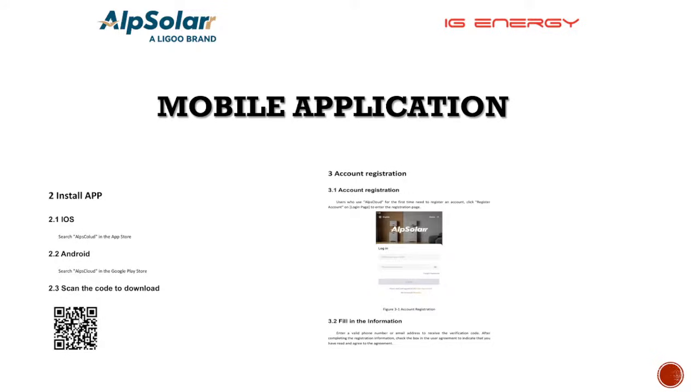But can I ask a question? Yes. What's the disadvantage of it? The disadvantage is that when there is an issue or something, the client will start calling you as an installer, because once the client sees a small minor thing, they start calling, asking what's going on, why is this showing this? So now it's not left to you as an installer, from the comfort of your home, to go to the app and do a little bit of settings. Set the SOC, set the cutoff voltage, set all those parameters, and you see it working perfectly well.